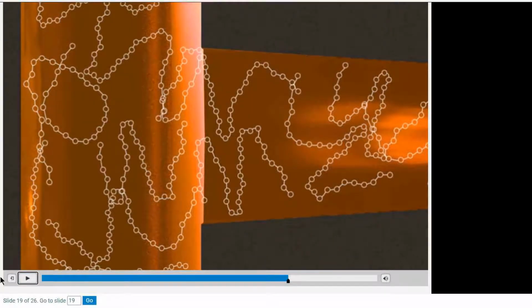So this has been a lot of information all at once here. So let's recap this just a little bit. Remember, when you have a material, if it's an amorphous or semi-crystalline material, you really need to know this because they do react to heat and cooling differently. So as a processor, make sure you get the material spec sheet and evaluate what material you are going to process. Then secondly, when you heat the material, the secondary bonding forces loosen up.